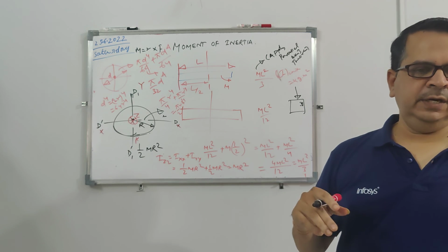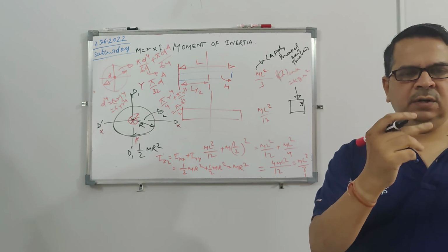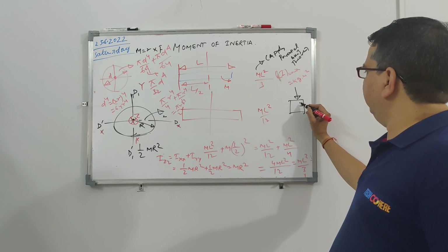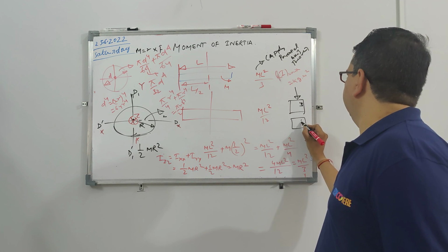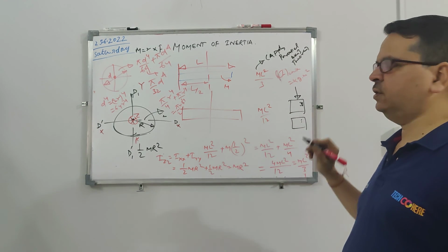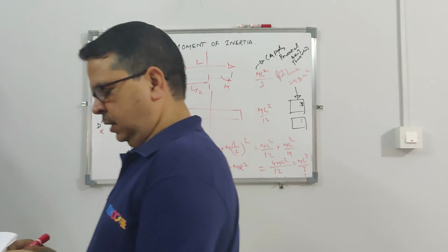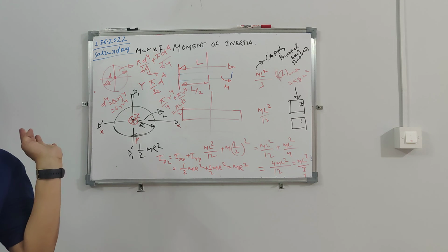But no body is truly rigid; the molecular distance will reduce and so on. So a rigid body is an ideal concept. If I apply a force, after some time the distance will reduce by compression, and if it is tension it will increase. A rigid body is one where there is no deformation, and Young's modulus and other such properties are all infinite.